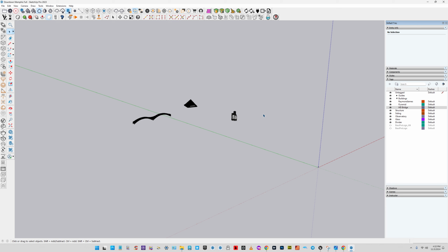And with the base of the floor for my project being underneath the grid, I had to extrude the floor back up to 0, and I used a line to give me the measurement of how much I needed to extrude the floor back down underneath the axis, so that once I scaled the model into place using these little lines I created at the axis point, I could then extrude the floor back down where it is based on the imported assets.